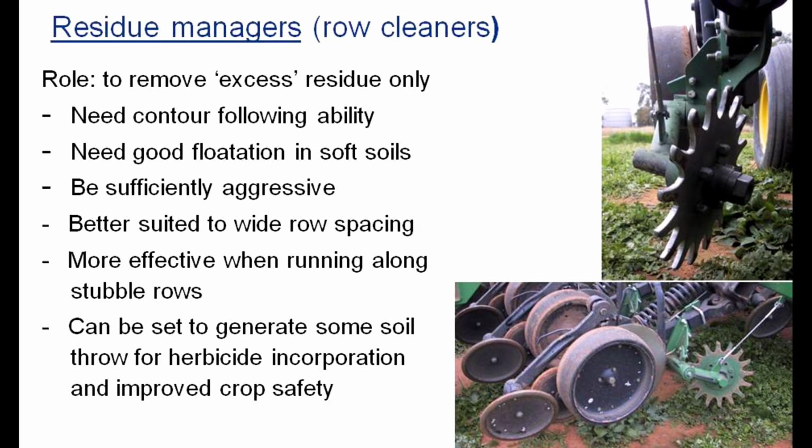And the other option is to use residue managers. These are designed to push residue across, essentially to get residue out of the way of the disc and control what the disc sees while operating the furrow. Why don't disc seeders track as accurately?